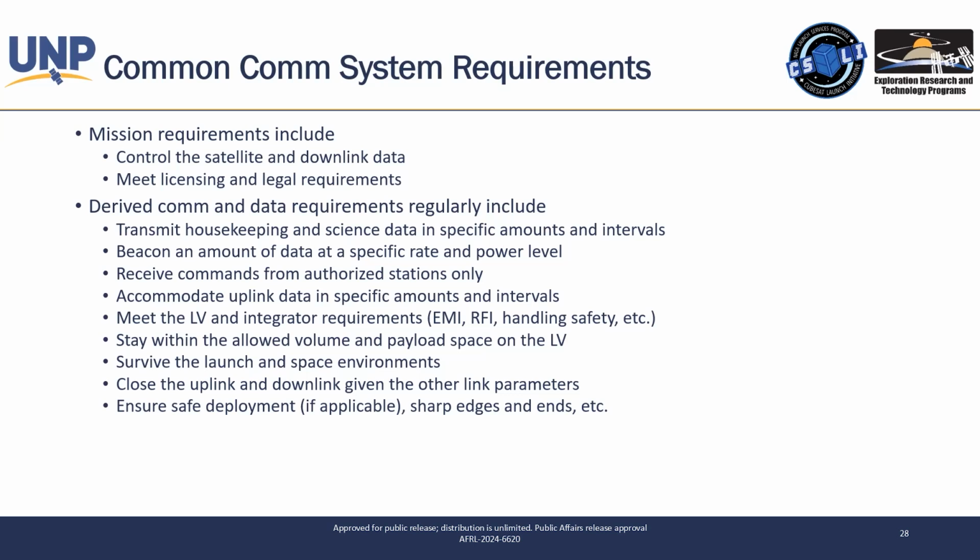So a lot of times they'll use a lower data rate transceiver just for handling telemetry and command. And then they'll use a very high data rate transmitter, pointing it at the ground station and just dumping the data. That's a pretty effective architecture I've seen work on a lot of satellites.